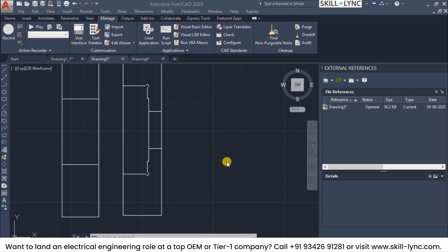So next is a great addition apart from the AutoCAD interface. It is called the Design Center. This Design Center is something you can use to organize access to drawings, blocks, hatches, or any other drawing content. It simply means that you can drag content from any source drawing to the current drawing. It is a quick reference of all your existing database, all the existing block references, all the existing drawings, so that you can quickly drag and drop. So this is like your own personal Jarvis, so that you can quickly invoke whatever you want into this drawing.